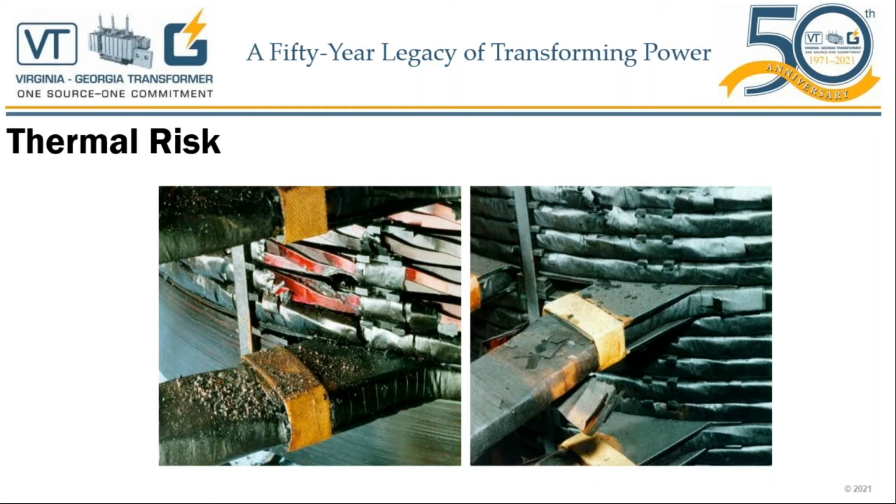One thing I do want to emphasize in the picture on the left, though, is you can see the second and third conductors, the discs, actually have arced. That is a dielectric failure. So what I'm pointing out here is, as our insulation degrades, ages, and starts to fail, that is going to cause the insulation integrity of our transformers to be reduced.